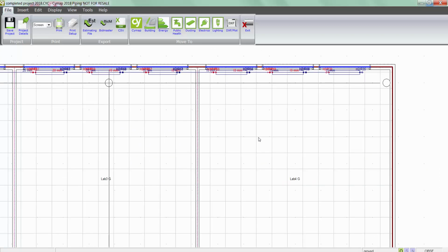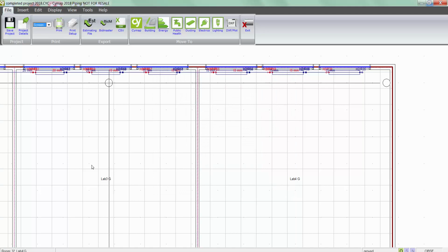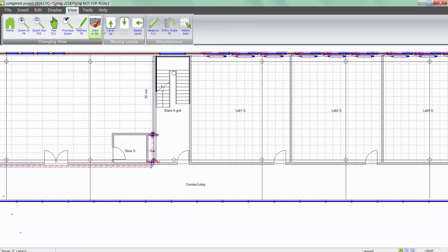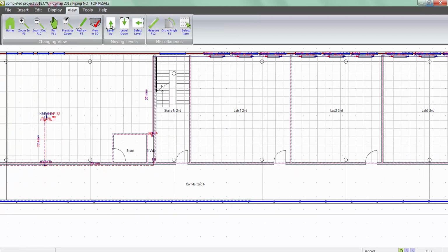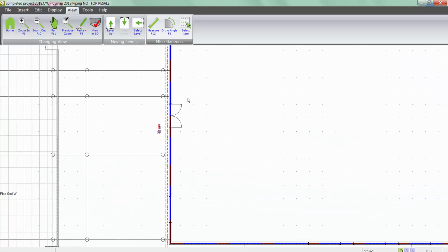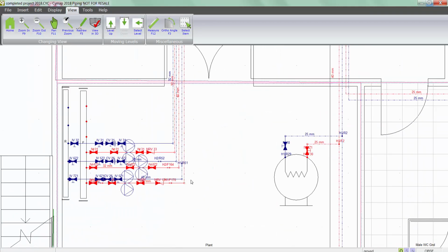Based on the heat losses to the space, the user can effectively place radiators, determined by the windows if necessary. The engineer can then route the pipework on the floor plan, up or down through the building via riser positions, to a position in a plant room where the engineer can connect headers, boilers, and add symbol libraries to represent pumps and valves.